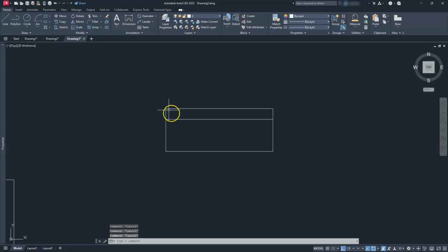Okay, the last step I need to do is tell it how deep to go down in this direction, and that depth is sitting at 8. So that's just going to be another offset of 8 going back this direction. Alright, let's go ahead and trim this.